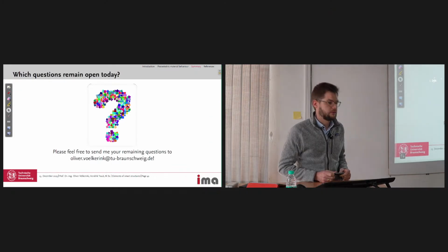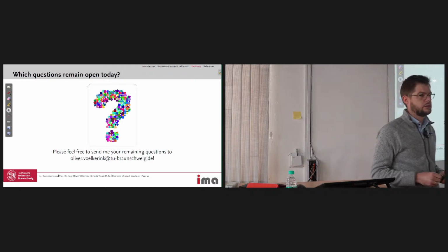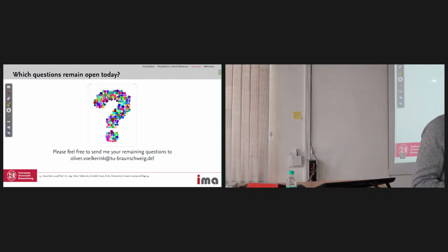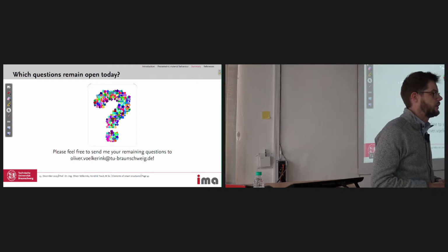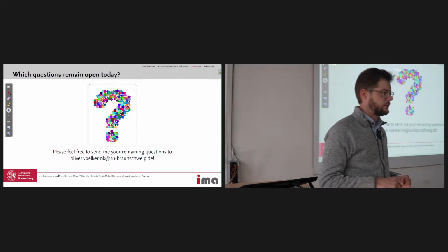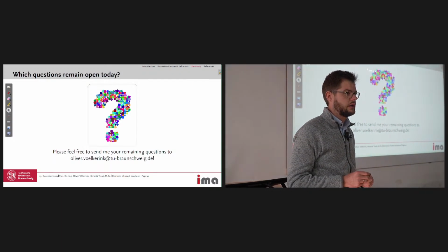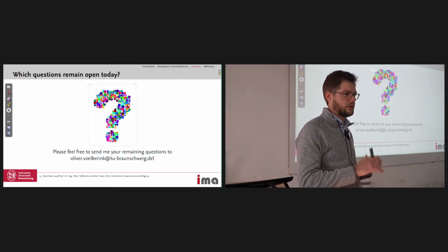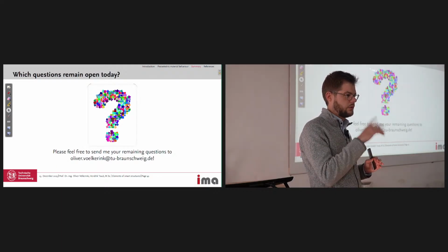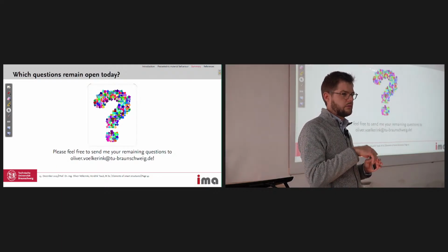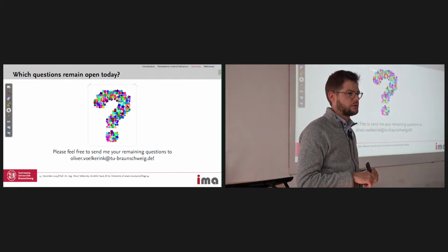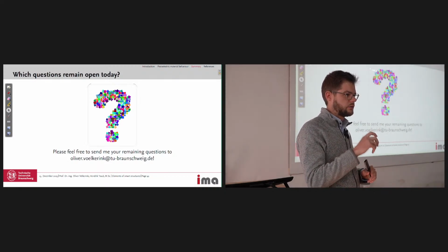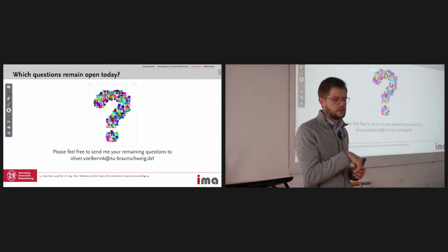Dynamic behavior, like alternating current? Yeah, it can create a lot of heat and operational problems. I think the piezoelectric material is quite good for dynamic behavior, because you also use it for structural health monitoring, where you excite the structure with a burst signal, so a sine wave with different amplitudes, and also collect it with the sensor again.